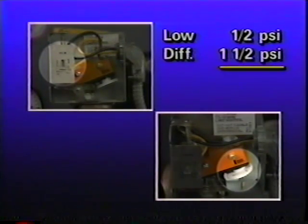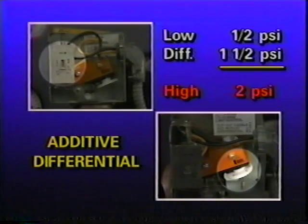This would mean that the pressure control would cause the burner to stop operating at 2 psi, which is the low setting plus the differential setting. This can be referred to as a pressure control with an additive differential.